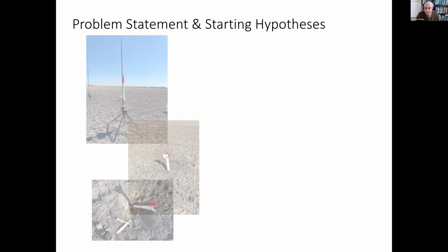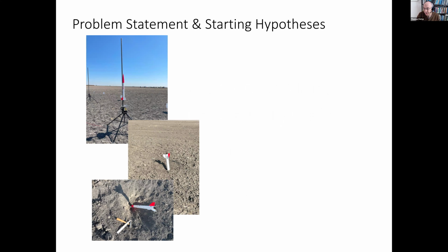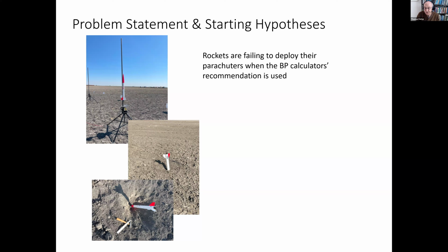So I was concerned when two new rockets experienced recovery failures, each on their second flights, both failures on the same weekend. What was different about these two rockets was they used recovery blankets rather than the pistons that I had mostly been using on previous rockets. I had always used the online black powder calculators to determine the amount of black powder, and that had worked for the pistons, but I needed to understand the reasons for these failures before flying these rockets again.